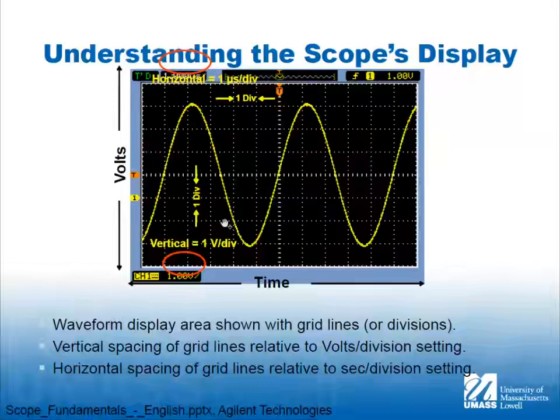I don't know or care how many samples it is right now. If I was really looking to find out what the accuracy of a scope was for a specific measurement, then I would look that up. But for now, just know that I have a time base that's sampling this signal, and then a vertical measurement that converts a continuous signal coming in to a sample. An 8-bit sample, 12-bit sample, whatever the vertical resolution of the scope is.